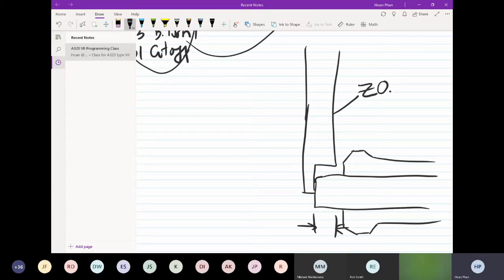So the first thing we need to know is, where is this position right here? We have some information in order to calculate it, which is the width of the tool. In this case, the pocket for this tool, pocket number 1, is going to be 5/8. So 5/8 is .625.